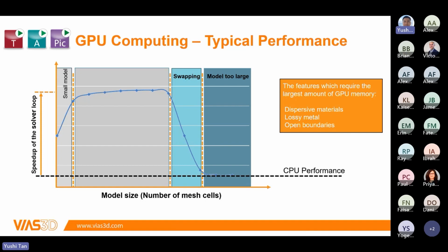So, if we are running this in batch mode on an AWS server, I can only see these messages later in the log. Yes, if you're running batch mode, that is very true. So using the 8 million rule of thumb should give you a very conservative estimation as to how big a model your GPU can handle. And of course, you need to know beforehand how much RAM is on the GPU itself.